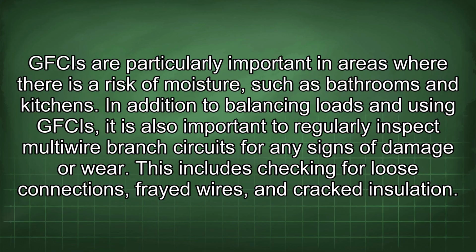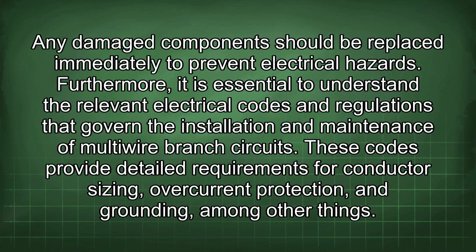This includes checking for loose connections, frayed wires, and cracked insulation. Any damaged component should be replaced immediately to prevent electrical hazards.